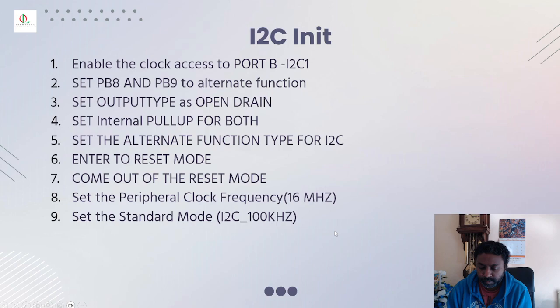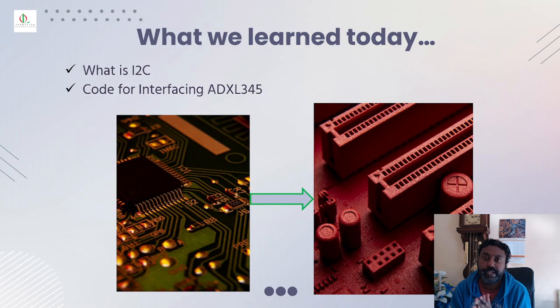We learned about what the I2C is and what all the different registers are that we're going to use, the different message formats, sending the address frame and the data frame, and the acknowledgement bit and the read and write bit. In the next session you will be learning more functions to link those address frames and data frames. And then there is another dedicated session where you will interface with the ADXL345 and you will see the demo in the PulseView logic analyzer.